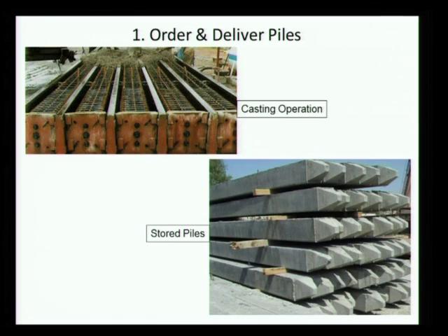When we say order and deliver piles, what we have assumed is that a precast pile is available from a fabrication factory to order and deliver. If you have not visited a precast yard, it is something which you should do as a part of an industrial visit. You will have molds like this into which concrete is poured, and then it is stripped, cured, and you will have piles ready for delivery in this form.